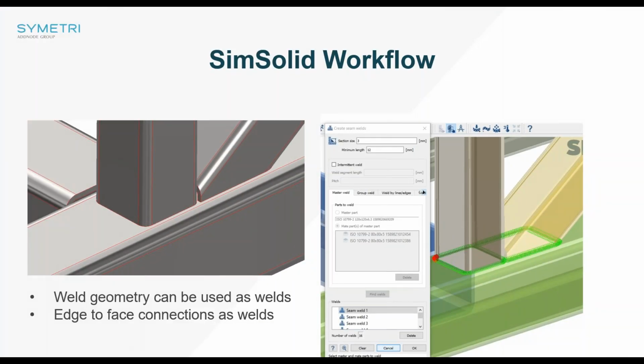In essence, I just want to go straight into SimSolid and show you. Here we have a weld geometry. Here we don't have welds. So what happens is, in this example which we did on a frame 2 weeks ago, SimSolid will create edge to face contacts. This box section here, you can see it will create an edge contact to simulate the weld. It is not simulating the actual weld size, it is simply contacting the edge of this box section all the way around onto the face of the frame, and that's how it works.